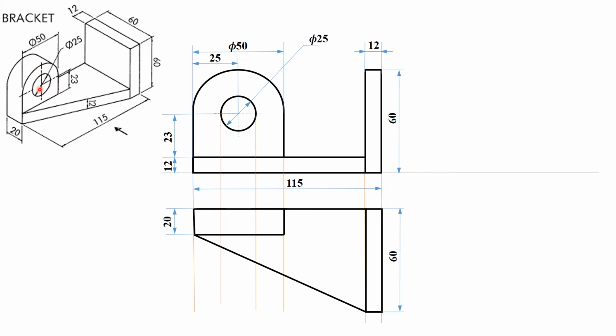So that will be given as a hidden line. This is the extremes of the hole. This is the diameter of the hole, which you can take from here. The hole will be running through this region, yes or no? So it will be given as a hidden line. This marks the top view of the hole, which is hidden. So that's how your top view is finished.